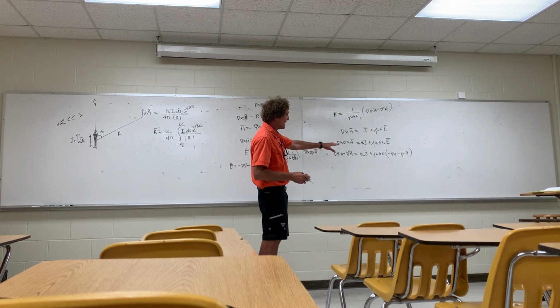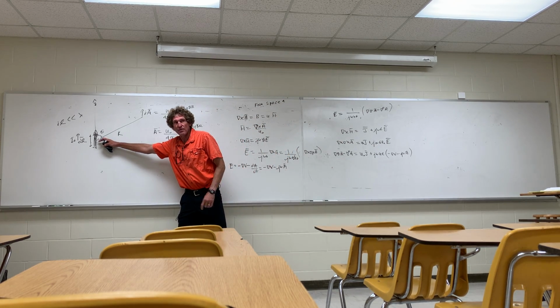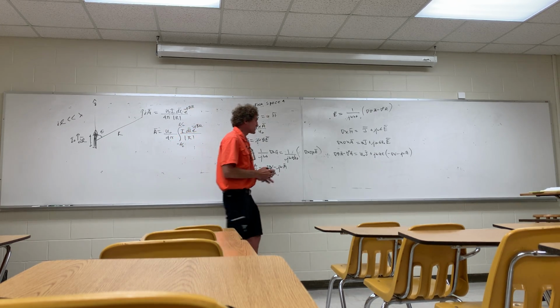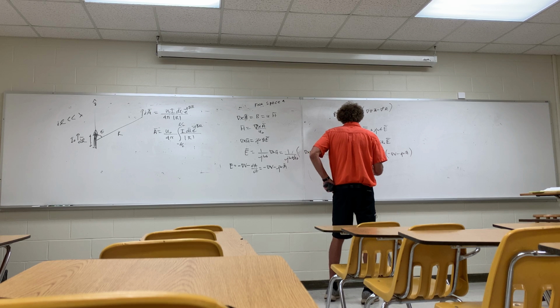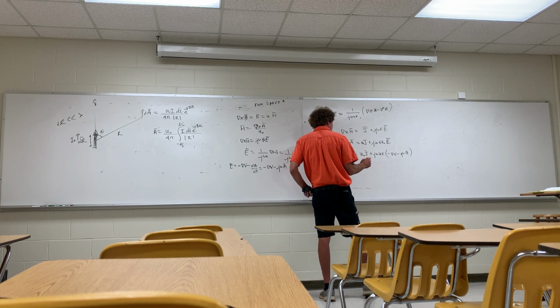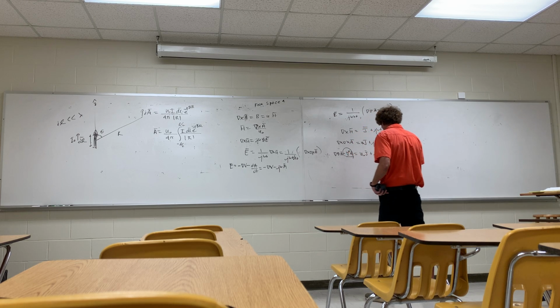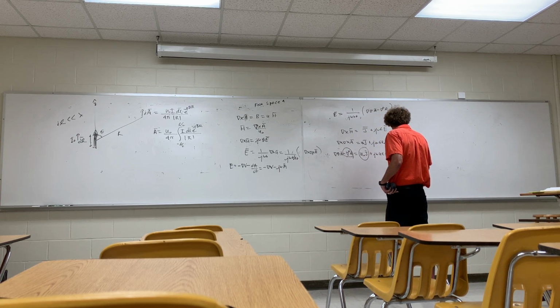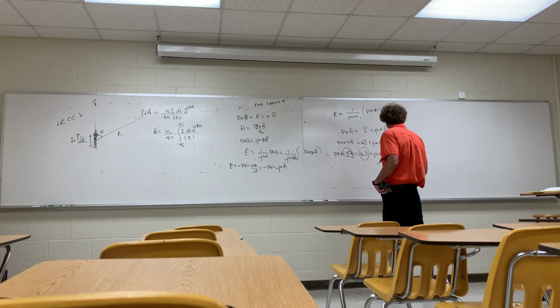So now I've written everything in terms of both J and A. J will be a source current, this current right here. Y'all follow me? There is no J in free space, so this is going to be a source current. They take this term right here, now it's separable, and this term, and this term, and they make them the same.